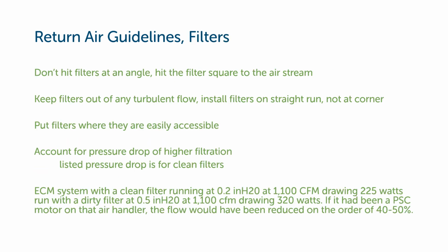Here are some more return air guidelines, this time pertaining to filters. I think the big one is don't hit the filter at an angle. Make sure that the airstream hits square to the filter. If the filter's tipped at an angle, it actually creates more impedance to the airstream, which makes more noise.